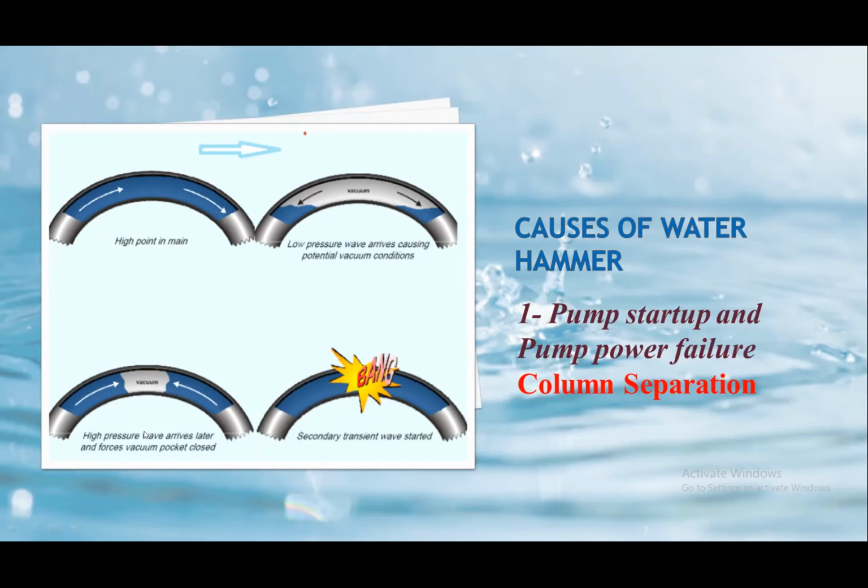So the column at the pump direction is going to move towards the column at the destination direction. Well, if this column is moving at really high velocity, of course, because it's a pressurized system, that will lead the two columns to collide together, causing pipe rupture and pipe fatigue. Okay?